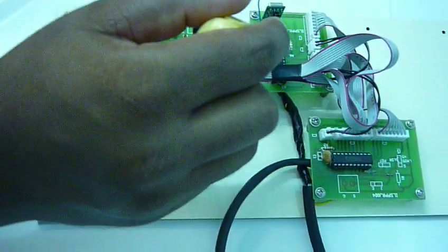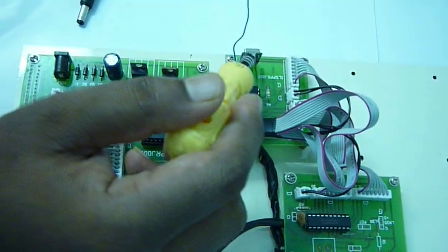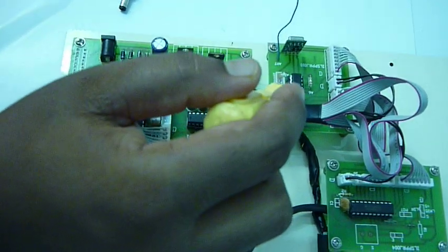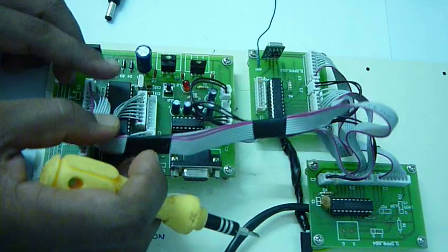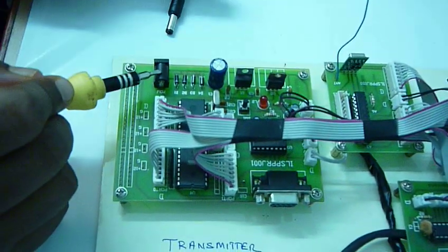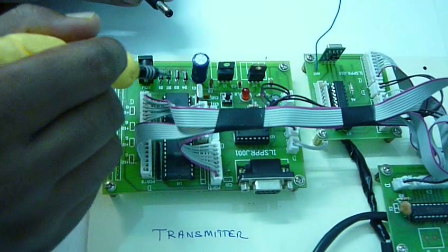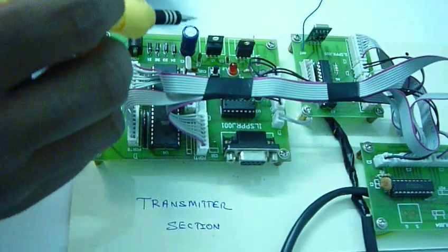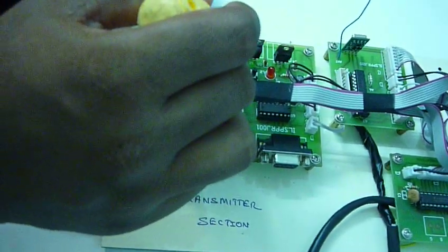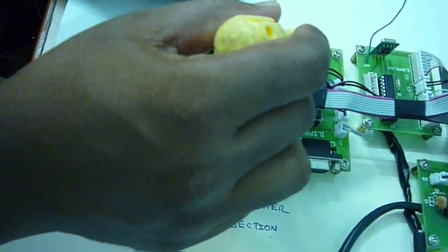The wireless transmitter in turn sends the information to this antenna by a transmitter module. This is the transmitter module, and we are using an encoder IC here which encodes the wireless data. Okay, so coming back to the main microcontroller, we have a power input here. We have to supply 12 volt AC, which is then converted into DC by a bridge rectifier of 4 diodes, which is then filtered by a filter capacitor, and then regulated by a couple of regulators. One is the 7812 regulator, which gives you 12 volt output. The other one is the 7805 regulator, which gives you 5 volt output.